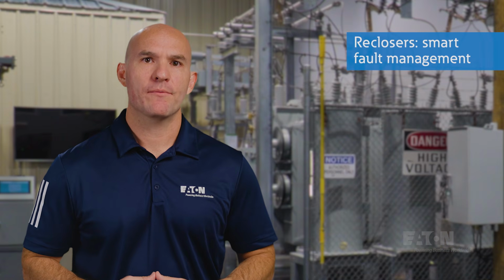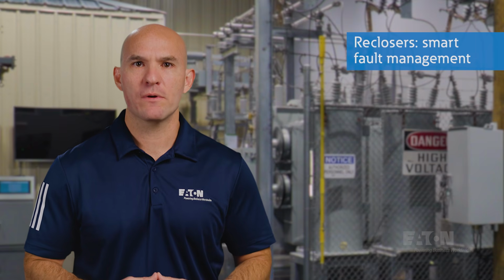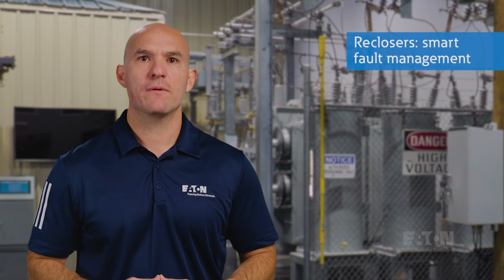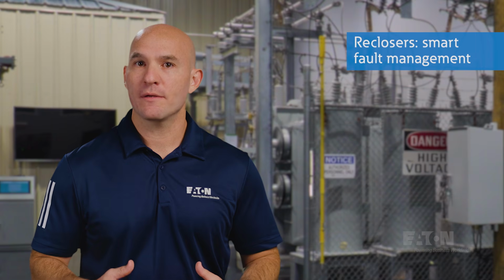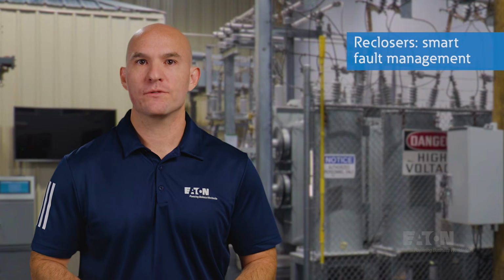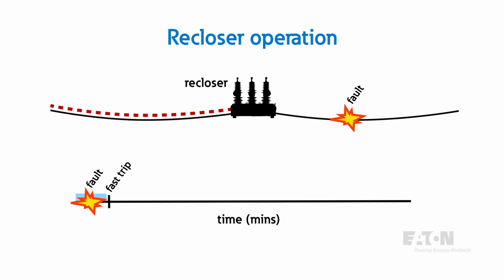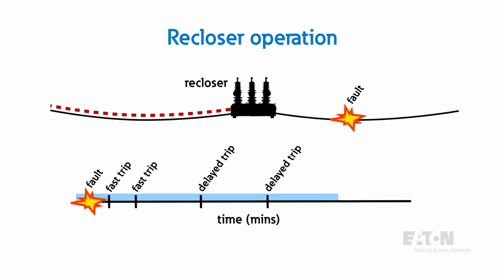Now let's talk about reclosers, devices designed to open and close up to 4 times, giving temporary faults a chance to clear with a momentary interruption, without causing a sustained outage and requiring the utility to roll a truck. A typical recloser sequence includes 2 fast trips followed by 2 delayed trips, giving the fault multiple chances to clear. If the fault is still present after this attempt, the recloser goes into lockout.